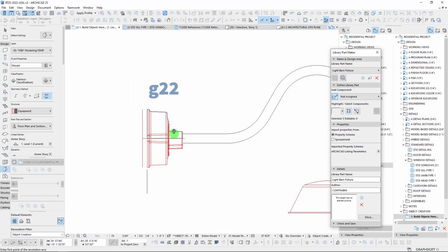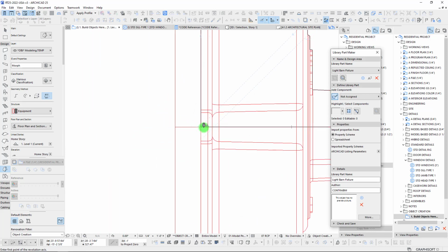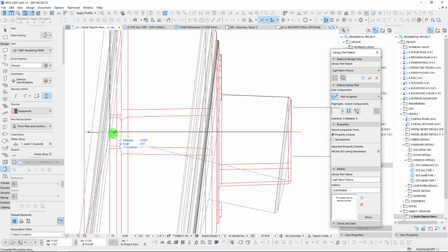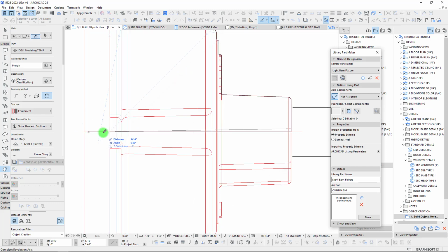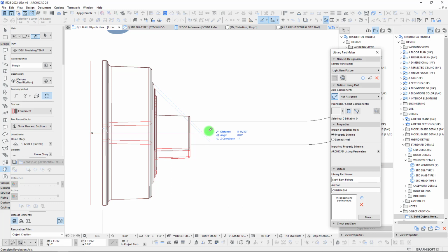Now this next step is really important. We need to enter the first point of our revolution axis, which we want to be directly on this line here. It doesn't need to be inside. We can go on the outside, but we need to pick, and then we need to make sure that we are getting that preview of that full rotation there.